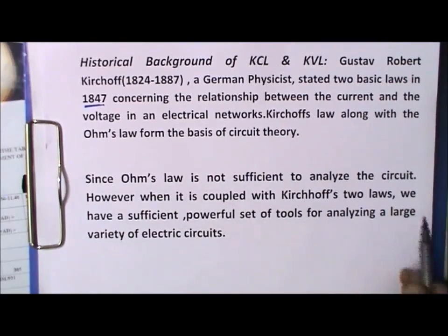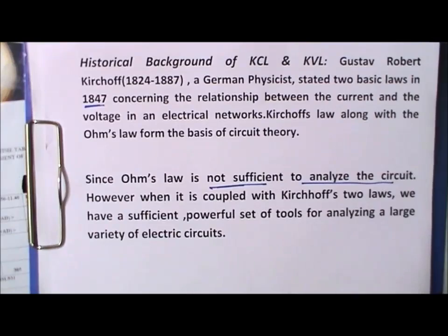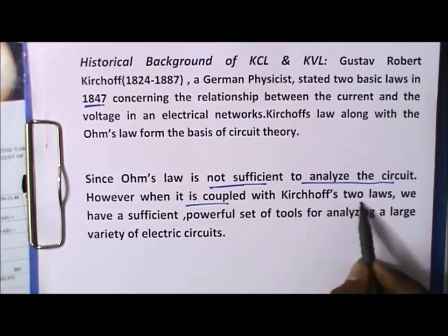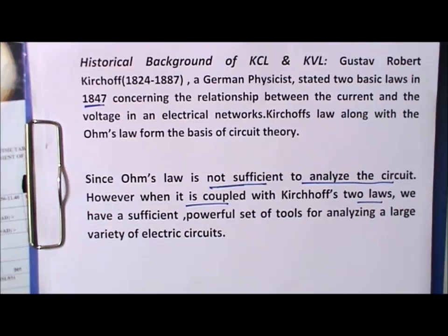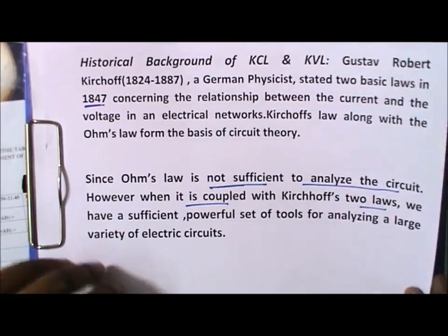Ohm's law is not sufficient to analyze the circuit, and there are some cases where we are not able to solve the network circuit just by using Ohm's law. However, when it is coupled with Kirchhoff's two laws, we have a sufficiently powerful tool for analyzing a large variety of electrical circuits. So if we are solving circuits, we have to use two basic laws, first the KCL law, second the KVL law, in addition with the help of Ohm's law. So let us discuss one by one what the laws are about.